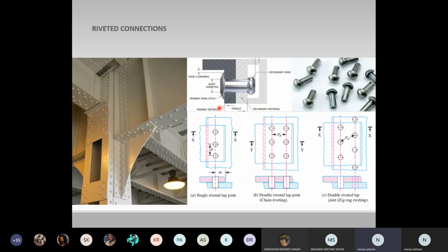The process of riveting is conducted by inserting the ductile metal pin or rivet into the holes of the pieces to be joined together, and forming a head at the end of the rivet to prevent each metal piece from coming out. The shank of the rivet is made of a length to extend through the different parts to be connected, with sufficient extra length for a second head to be made.